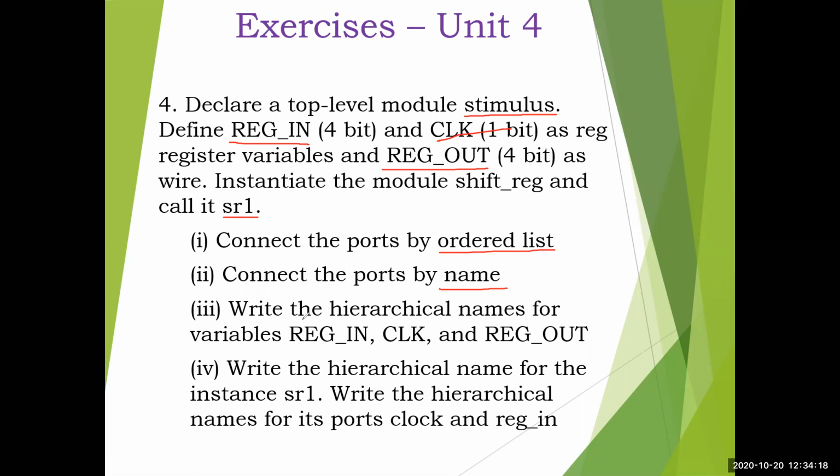Then third stage, you write the hierarchical names for variables register in, clock and register out, which are inside this stimulus module. Using the dot operator you write the hierarchical names. Then similarly write the hierarchical name for the instance sr1, and also for its ports, clock and register in. Inside that you have the 2 inputs, so that also you need to write. Simple. We'll do one by one.